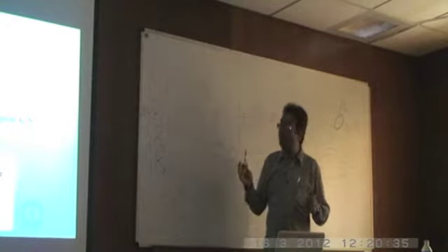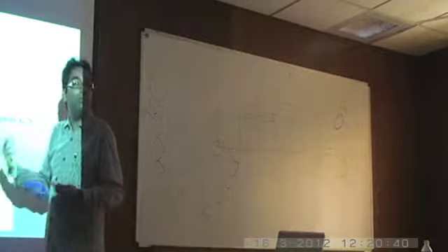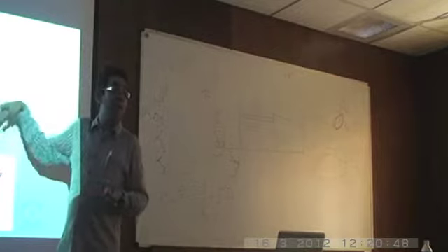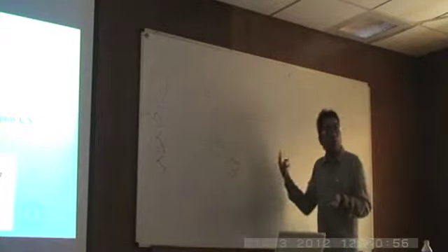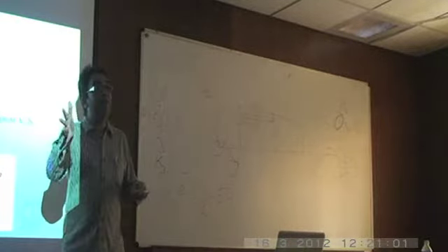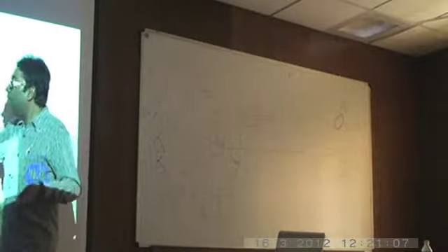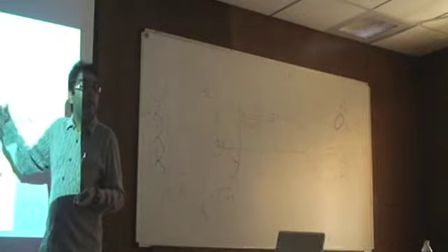So that's your S12 that we are looking at. First of all, it is an off-diagonal term. Secondly, this is something which is more commonly observed, or it just comes into prominence in open cross-section beams, unlike here which is closed cross-section beams, but both are thin-walled. Okay, so unless and until it is thin-walled, your warpings are not large enough. If you have a solid cross-section or very thick-walled closed or open cross-sections, the warpings are not significant, and therefore the in-plane warping in particular is not much, and therefore the change in stiffness is not much. So there are some similarities between these. There are also some differences between these.